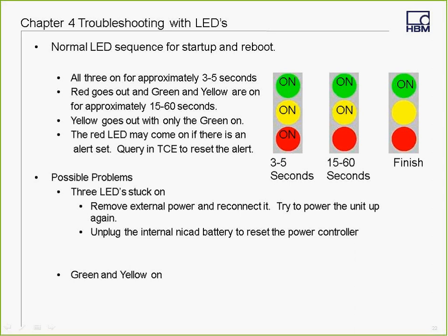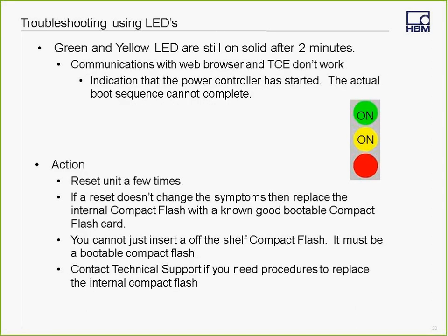Green and yellow stuck on usually means that the eDAQ has not finished the boot up sequence. If you're unable to communicate via the web browser when the eDAQ displays this LED sequence, it is an indication that the boot up failed early in the process. Oftentimes it is an indication that the boot compact flash card is faulty or corrupt.